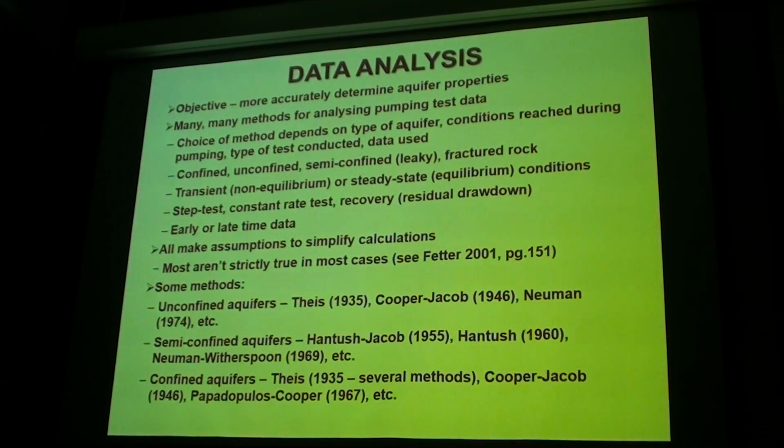Unconfined and confined aquifers are very different to calculate for, because in an unconfined aquifer, as you pump, the aquifer starts draining, and so the saturated aquifer thickness changes all the time. Right? The amount of the aquifer saturated changes to take water out of it. In the confined aquifer, it doesn't, because the confined aquifer is always saturated. The piezometric surface drops, but the aquifer thickness is always saturated with water. So these are the ones you should be targeting most of the time. But either way, the people have done all the hard work for you.